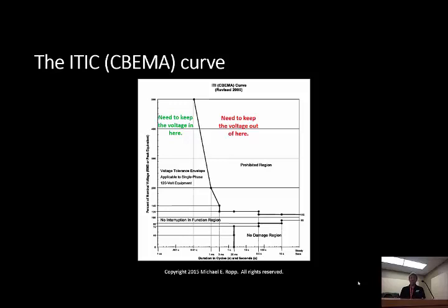And I'll tell you right up front, that's a little bit of an abuse of this curve because it's really not designed for this. But what we would really like to see at some point is some kind of a set of curves that is based on damage curves for different types of equipment, and then looking at what the most conservative points are at each point on the damage curve, so that you will get a criterion that can be applied at the feeder voltage level.